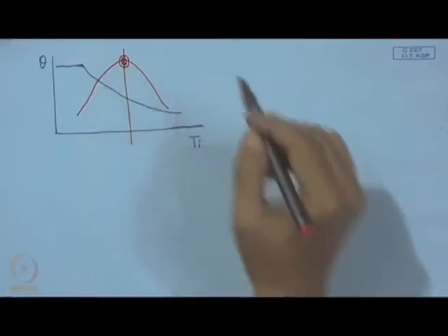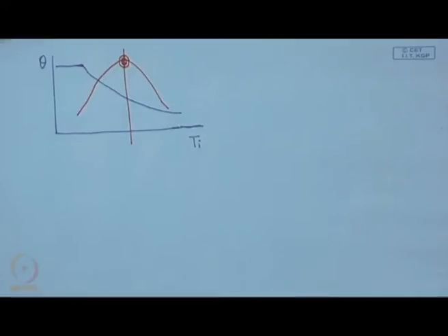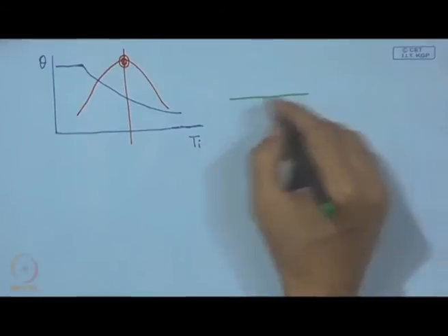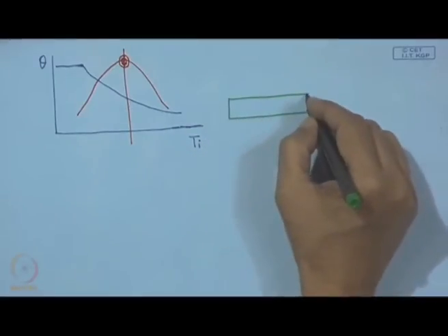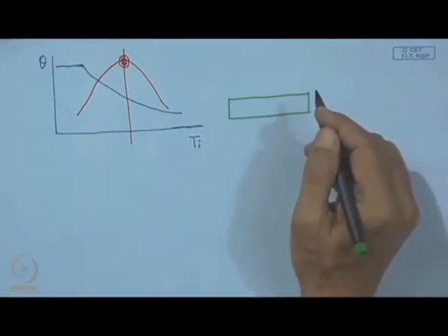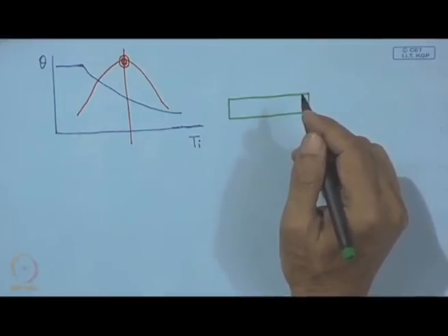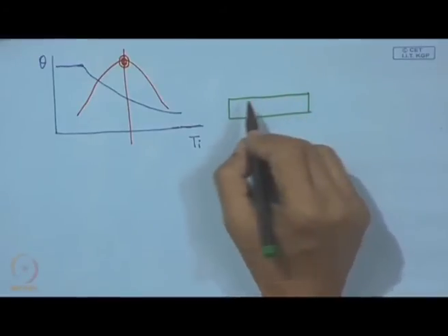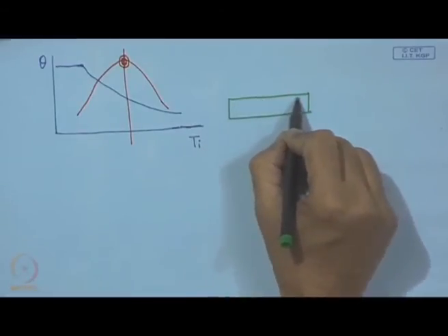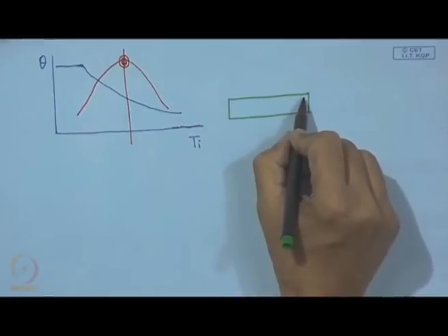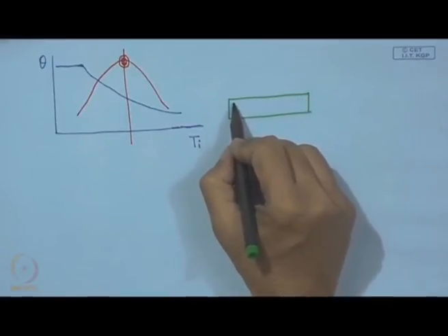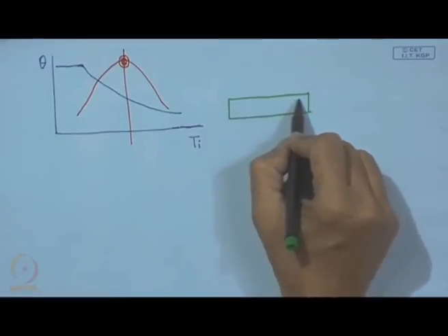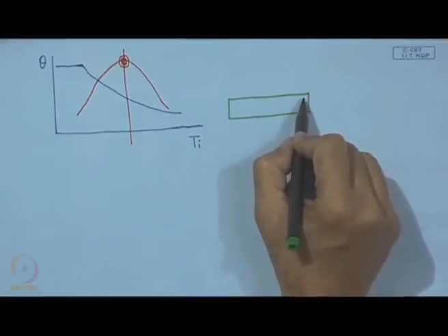Now, this can be explained by this simple fact that when it is a small amount of titanium, we do not have enough titanium to have this reaction forming a continuous layer. It is a continuity of the layer, and titanium should be continuously, uniformly distributed over the entire wetted surface.